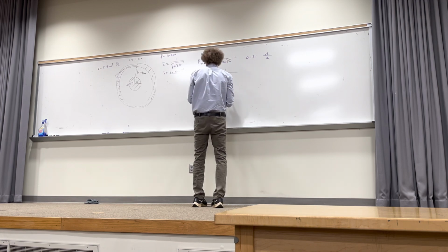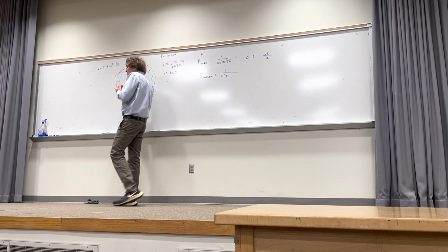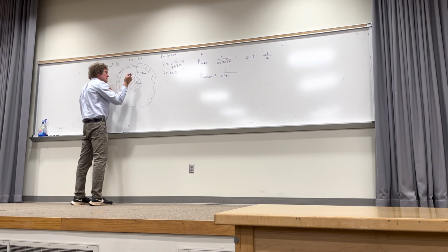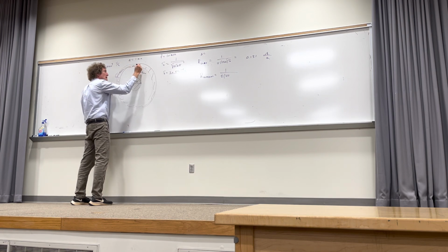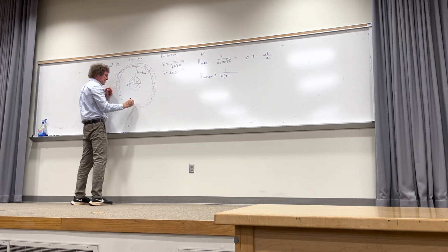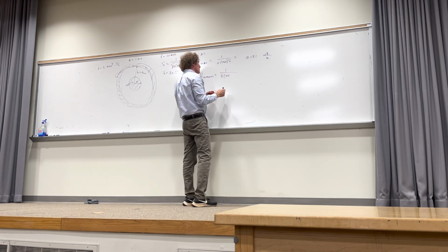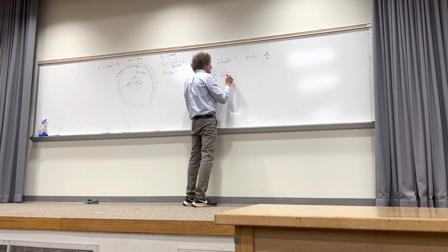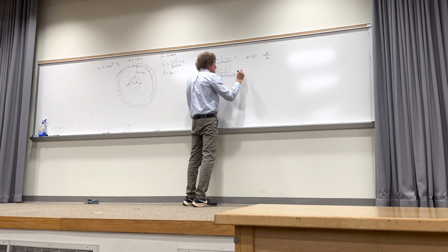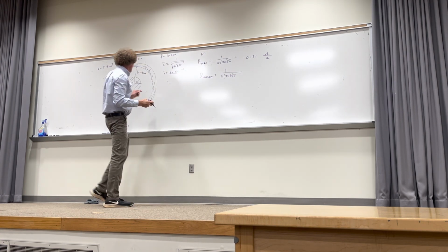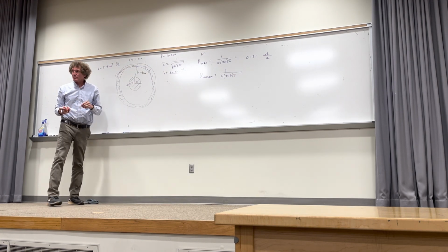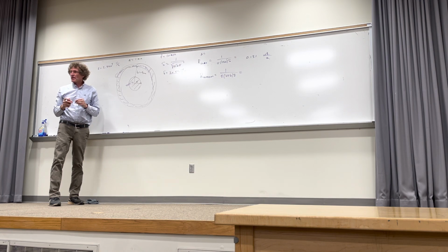And then for this outer conductor, you get the return resistance. Remember, current's flowing this way and then back this way. Now we have to go one skin depth deep here, and the only thing that changes, it's still going to be 1 over sigma, then 2 pi, times b times the skin depth. So the only thing that's changing here is this dimension, it goes to b. Y'all follow me on that?